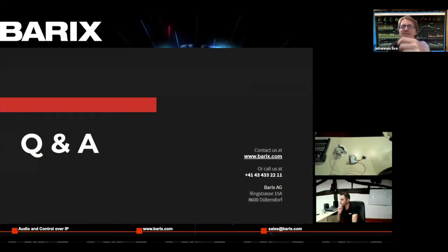So what does it have as an interface? It has, maybe you can see it or maybe not, just 2 wires. It's a 4 to 20 milliampere sensor. So that's one of those little jobs to connect one of those to a Barionet. Actually, it's trivial. You just need 1 resistor, and you can use a 12-volt power supply basically, and a resistor to make that a sensor which works perfectly on the Barionet's analog input.